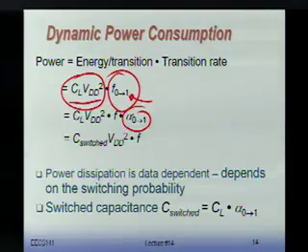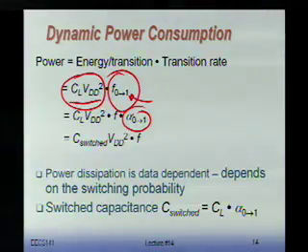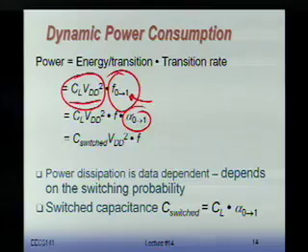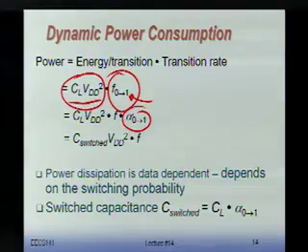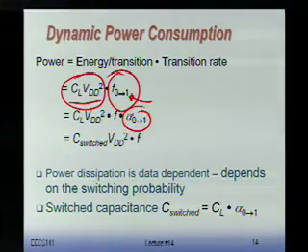So power dissipation is equal to, now, that's kind of a pain. This F01, I would like, when I have a synchronous circuit, to express my power as a function of the clock frequency. Right? F is the clock frequency. So the power dissipation would be CL VDD squared times F, but then I multiply this with an activity factor, which is the probability that on a clock transition, I will have a data transition. That's alpha 0 to 1. It's the probability that on a clock transition, my data will change.